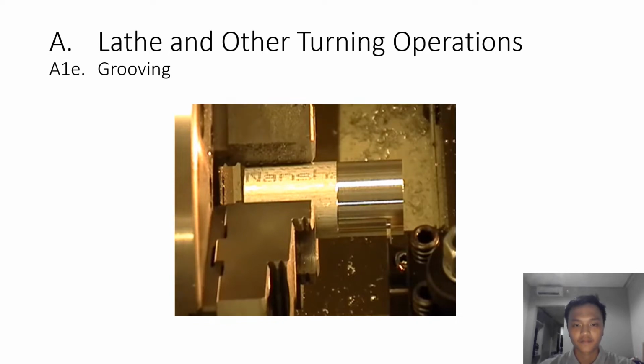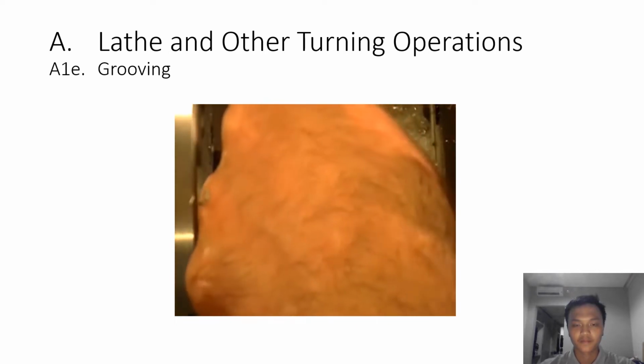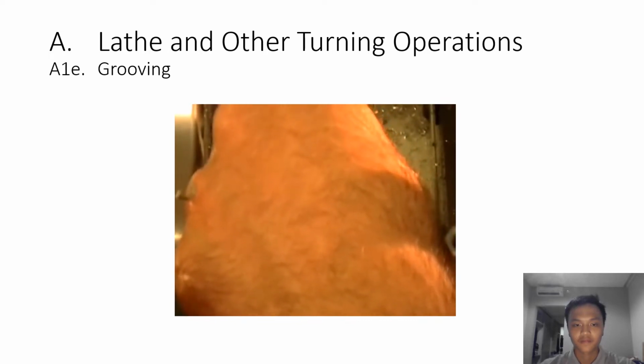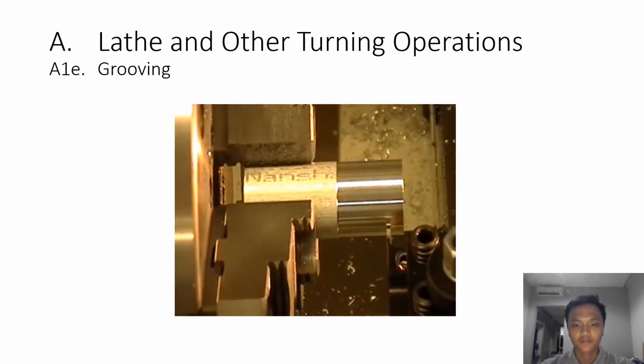So I'm going to measure the diameter on that right now. I'm using a caliper, but you really should be using a micrometer. I've got 0.984. So I add 8 thousandths to 0.984, and I get 0.992. That's giving me my X.